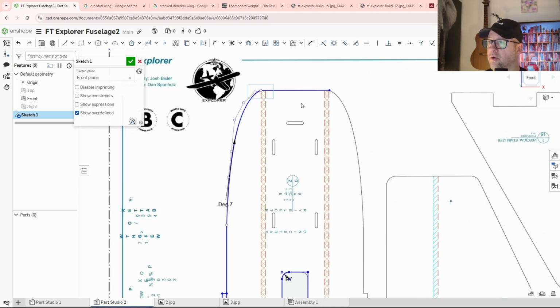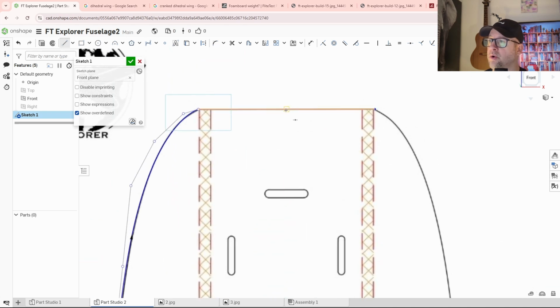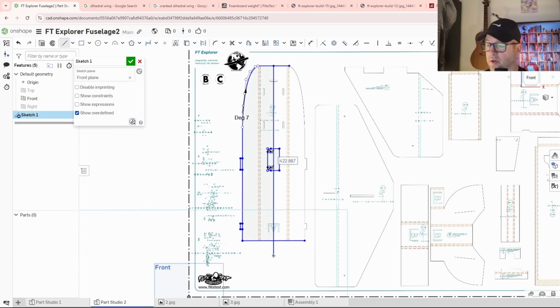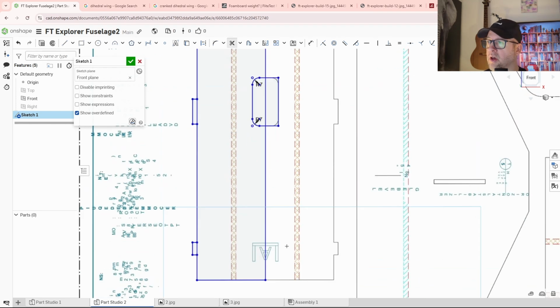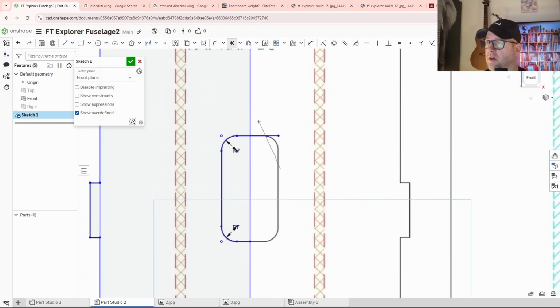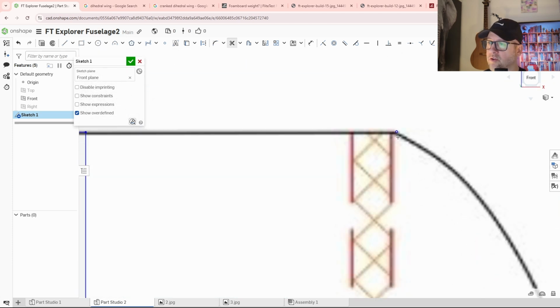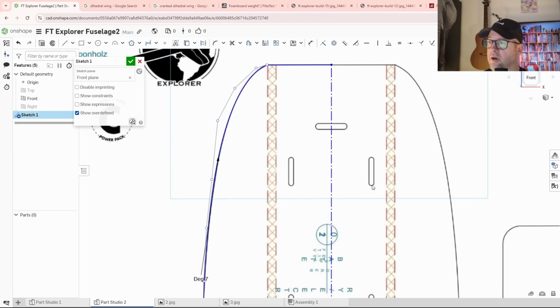All right, so now I'm going to build a construction line going straight through the center. Using the midpoint, so I find midpoint by just selecting that lower right hand side. We see the little midpoint line. That's exactly what I want. Go straight down all the way through. Hit escape. Now we can do some trim. So M for trim. I'm just trimming it. Trim that little dot. Okay, and then we can make this a construction line. So to do that, we click it and we go over to construction, escape, spacebar, get out of that.